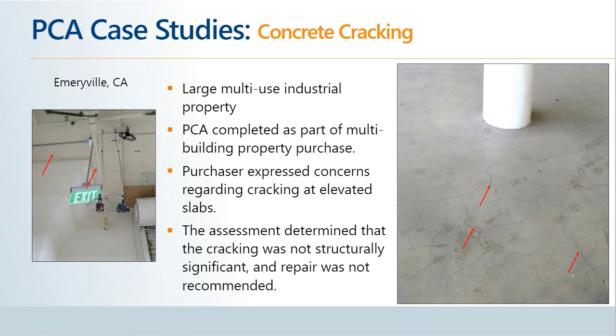The owner's concerns were not just limited to potential repair to address the cracking, but more so potential impact on the manufacturing operations of the space below, and quite honestly, potential costs associated with temporary shutdowns of that space. This cracking was able to be reviewed in more detail as part of the PCA, and very brief structural analyses were completed. These analyses ultimately determined that the cracking did not require repair, and accordingly, there was no need for a recommendation for any type of remedial action.